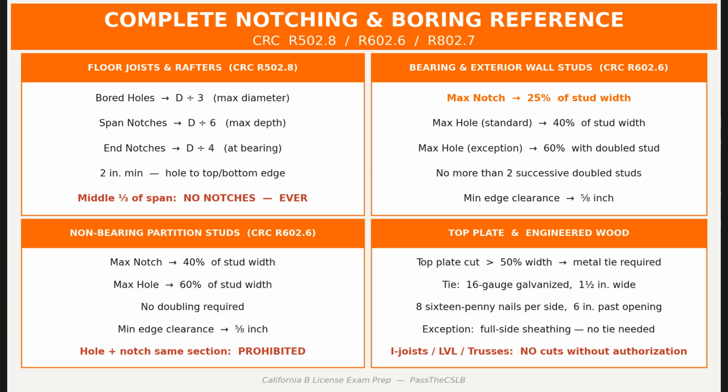The metal tie requirement activates at 50% of the plate width, not 1/3, not 40%. A cut at 49% requires nothing under R802.8.2. A cut at 51% triggers the full specification. Read the exact percentage in the scenario before selecting an answer.